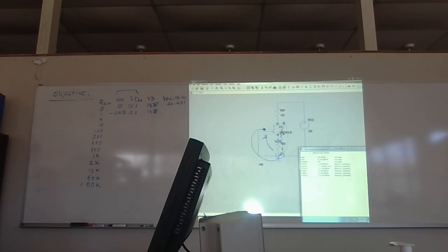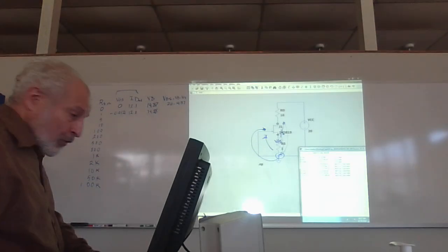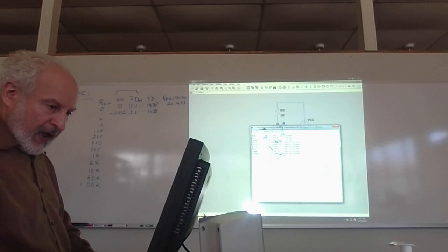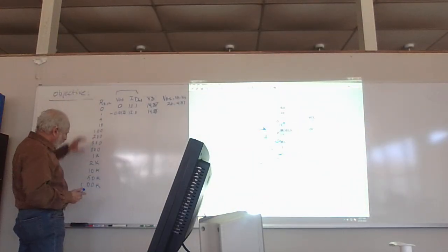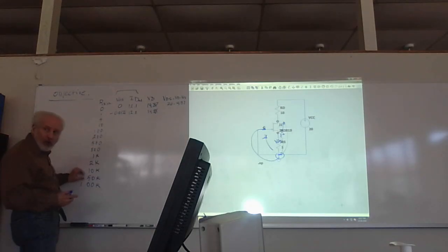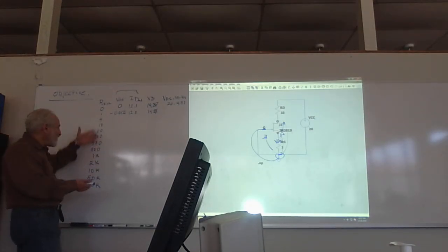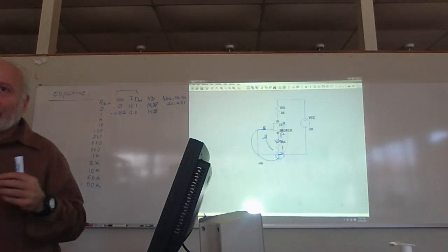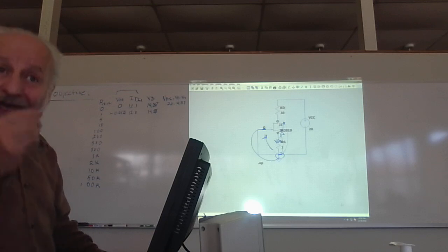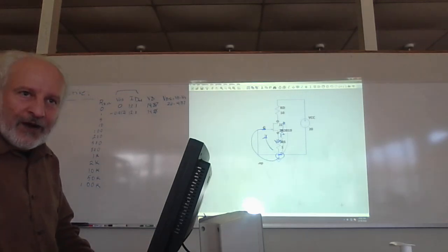Has everybody seen how I'm doing this? So I need enough points to see if I can get that transconductance with this. That's why I have all these values on the board here. So I'm going to go back, okay? And notice I spent a lot of time here just to see how it is there, and I should have a little more here just to see how it is at the end. This is pretty predictable in the middle, but at the end you want to really get the curve. You got it? So you may want to add more resolution there.